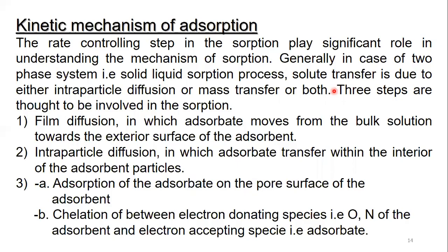Now, what is the kinetic mechanism? Basically the rate controlling step in the adsorption plays a significant role in understanding the mechanism. In a two-phase system, we are using a solid-liquid phase, so the solute transfer is due to either intra-particle diffusion or mass transfer or both. Three steps are thought to be involved in the adsorption. The first is film diffusion. What is film diffusion?